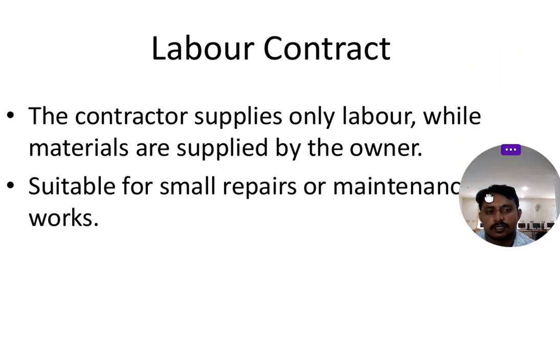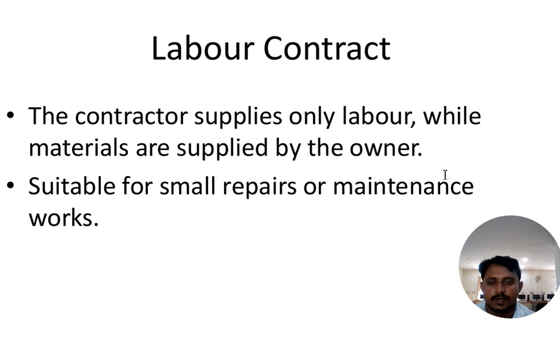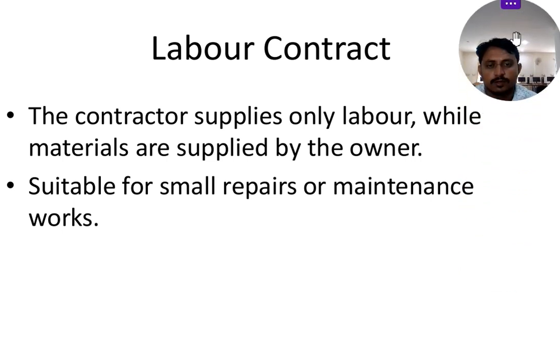The contractor supplies only labor while the materials are supplied by the owner. If the materials are supplied by the owner and the contractor supplies only labor, then it is called a labor contract. A labor contract is suitable for small repair or maintenance works only, whereas for large works or large repair works it is not suitable. So this is about the labor contract.